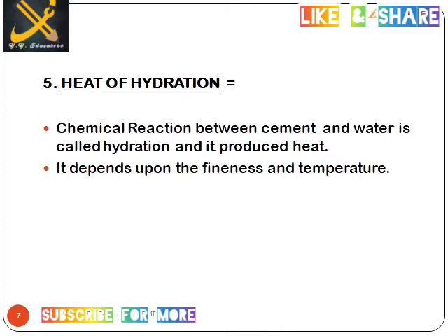The next property is the heat of hydration. A very important property. The chemical reaction between cement and water is called hydration, and it produces heat. The heat of hydration depends upon the fineness and the temperature.